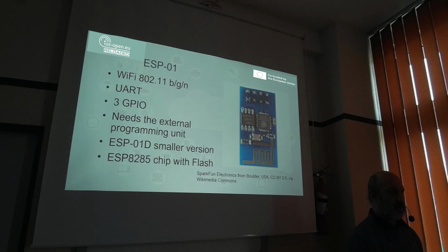Other connections are used for providing power supply and programming. It needs the external programming unit, but the benefit is that this is a very cheap element. There is also a smaller version named ESP01D that is very often used in, for example, remote controlled electric bulbs. I have found such an element in bulbs very often. It is based on the ESP8285 chip that has flash memory built in.